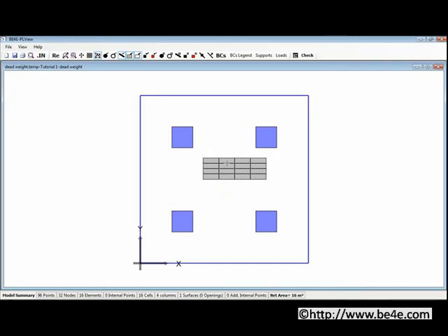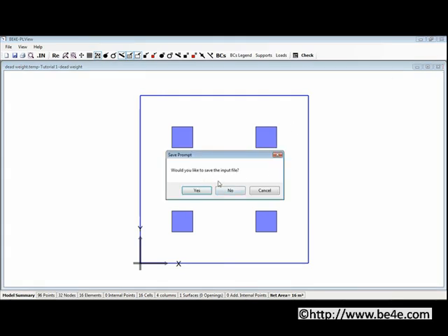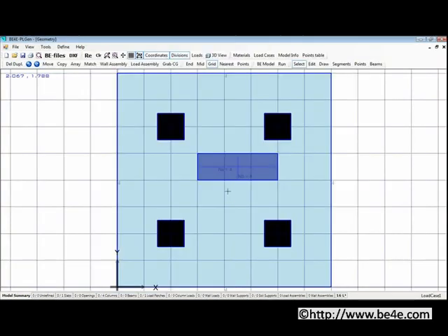In this case, I'm going to say no, but as you notice here, the number of divisions appear very clearly. Now, the number of divisions is usually taken between 4 and 8. Obviously, the more divisions, the more solving it will take, but the more accurate the results will be. Now I'm going to close that for the meantime, and it will ask you if you want to save the input file. We'll say no in this case, and we go back to the case that we were on.